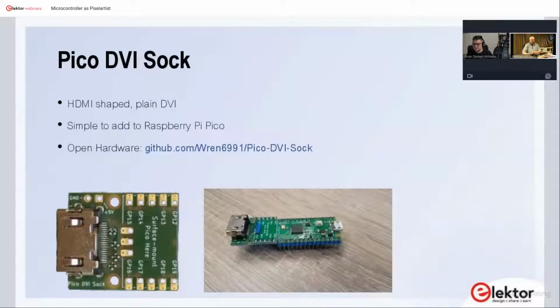and this has not changed. And the racing the beam approach is at that point, hey, I have graphics data, and I don't store a whole image in my system. I just have enough logic that I can create, with the information where something should be, a new image on the fly 60 or 30 times a second. So you just say where things should be. We will see that with a sprite sample. I think that makes that a little bit clearer.